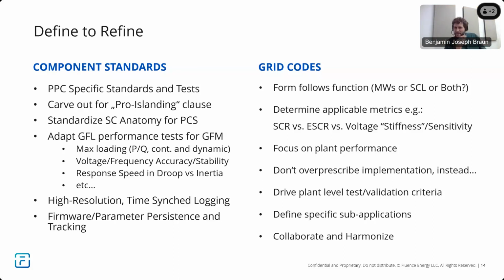You mentioned part of the question was grid following. In general, a lot of codes have adopted a response or reaction within not 5 seconds, but 5 milliseconds, and this is largely to kick out grid following. Maybe some very fast, low-level grid following could still do it in less than 5 milliseconds.